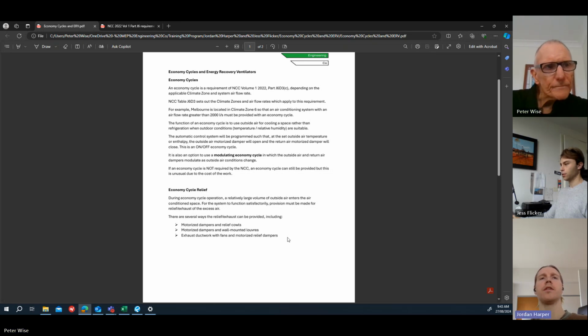I have a question before we move on. The economy cycle is operational all year round, so it doesn't matter what the temperature is like outside, or does it take that into account? Yeah, it's operational all the time. Well, it's available all the time. Right. So you have to account for the temperature of the air, the outside air coming in. Yes. So you have outside air sensors.